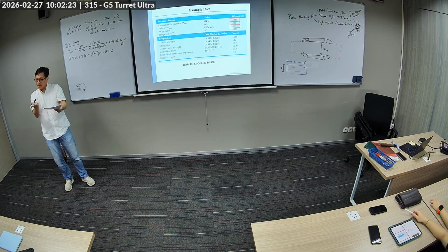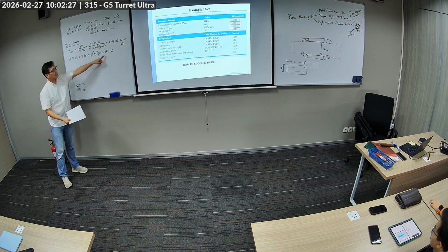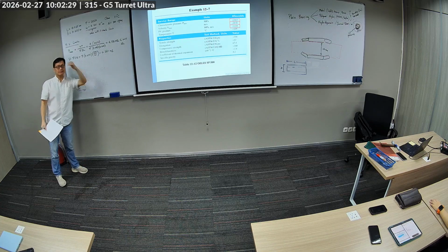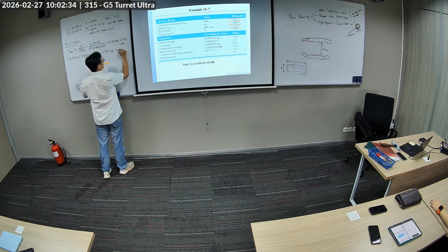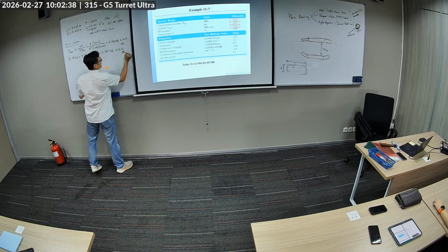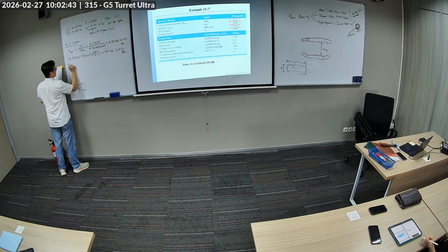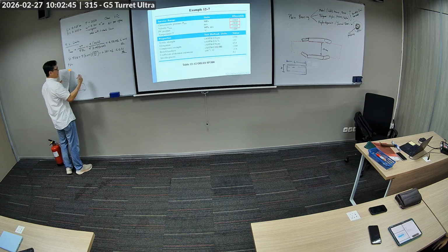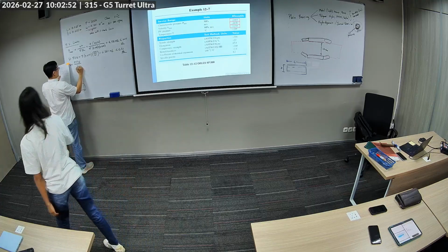So the shaft rotates, and if you open it up, the material interaction is like a linear rubbing, and that's the velocity of the rub. They have a limit of 0.51, so this is also okay. It's still under that limit. Finally, we have PV. So whenever you're selecting or evaluating a bushing, these are the first three things you evaluate other than wear and temperature.